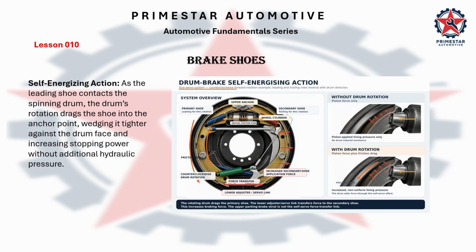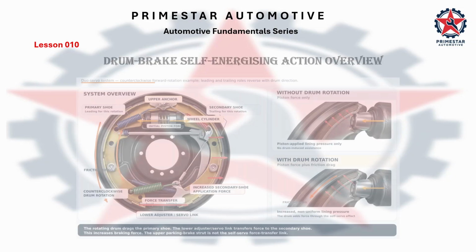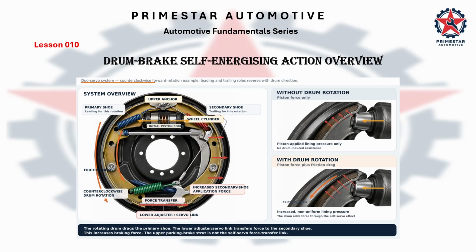Self-energizing action. As the leading shoe contacts the spinning drum, the drum's rotation drags the shoe into the anchor point, wedging it tighter against the drum face and increasing stopping power without additional hydraulic pressure. Here is an overview of a drum brake self-energizing action. I want you to be familiar with this one because this is very relevant when you are doing repairs or diagnosing.